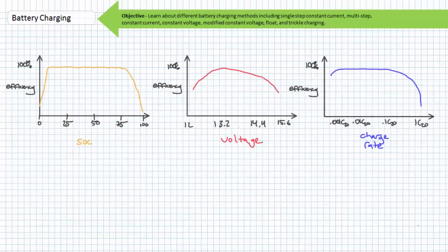Before we wrap this lecture up, let me briefly mention charge efficiency and the equalization process. Charge efficiency is the ratio of the energy actually put to good use over that supplied by the charger. Obviously, not all the energy supplied by the charger goes into beneficial energy storage, and some of it is lost to heat, destructive chemical processes, or other losses. However, you might be astounded to learn that the charge process can be very, very efficient.